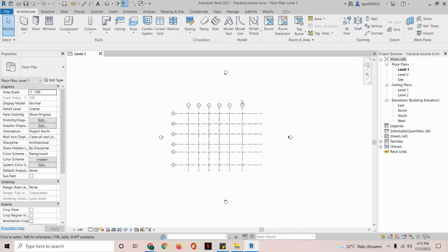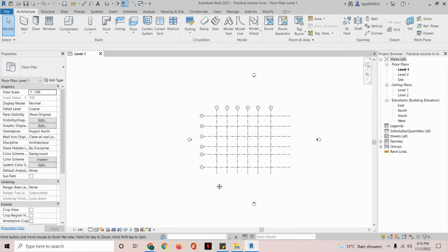So by right, when we are trying to do software, it's best if we have a mouse in which you can navigate properly. What I mean by a mouse is having a mouse that has 3 buttons. This way, you move left, you move right, it will be easier. If you see me on my screen, I'm moving quite a lot on my drawing area. So how do I actually move? It's actually pretty simple. If you click on your middle mouse button, it will become a symbol like this, and then you can pan your view.